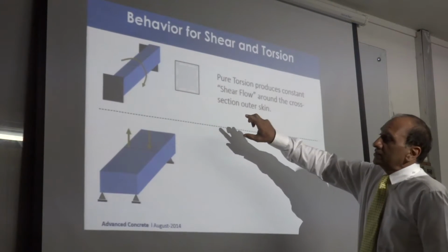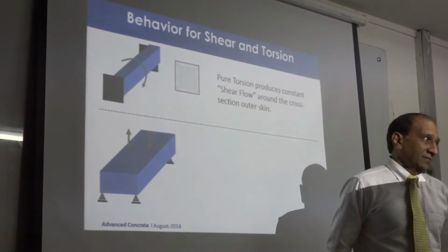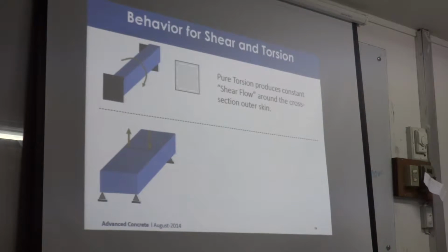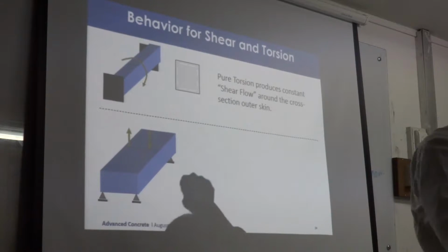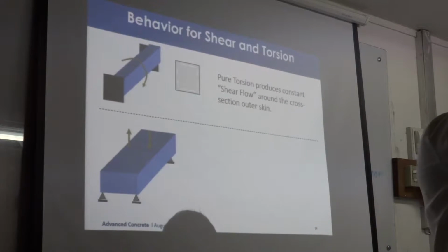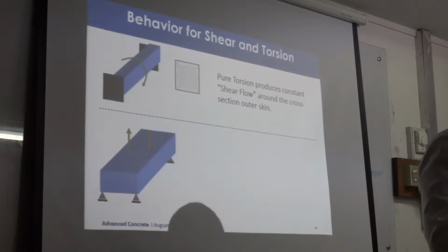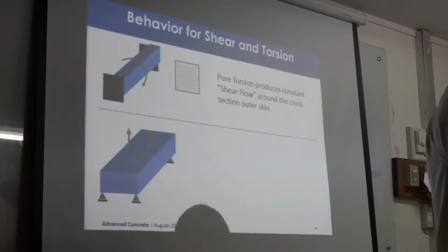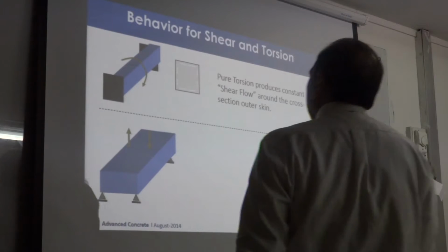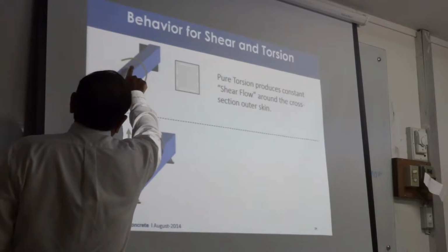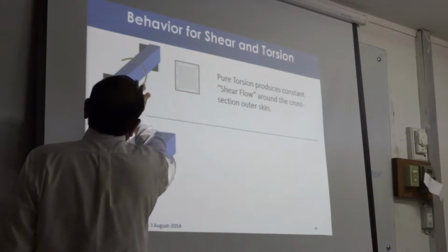The problem here is now we are talking about torsion. What does it mean to have torsion in a beam? Shear is clear. I told you it's cutting like a scissor. You take two parts of the beam and you just slide them across. Plain, pure sliding. Torsion is twisting the cross section. So twisting basically means that you have a cross section and you try to rotate it like that.